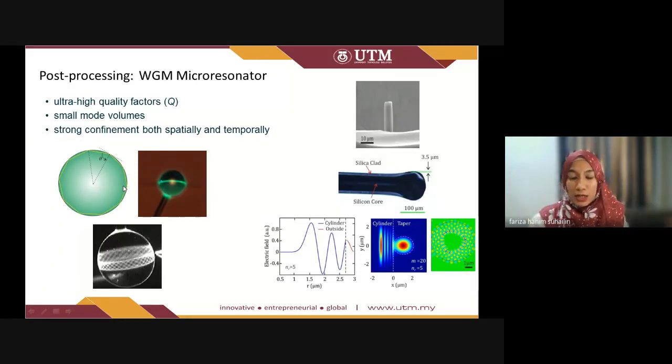What can we do on silicon optical fiber? These are among the resonators that I've fabricated. I etched out the silica cladding using wet etching techniques, and I also reshaped the tip of polysilicon optical fibers by using high power CO2 lasers, so that I can reshape the tip of the optical fiber to have this cylindrical shape.